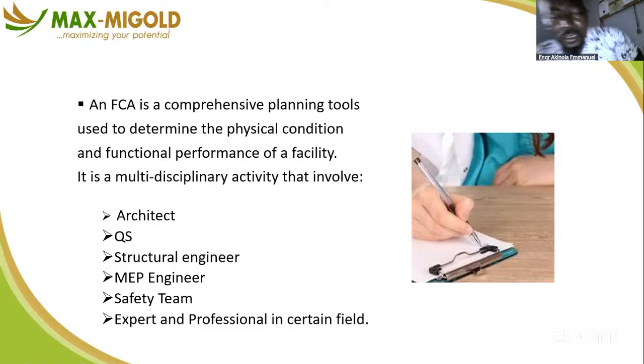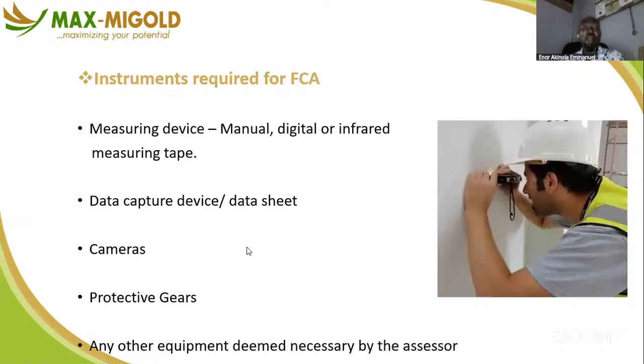You might need people to bring up possibly a drone for you to assess the external side of the whole skyscraper. For the interior, you can make use of your lift to take you to each of the floors. But in case you don't want to spend money on scaffolding, you can get a company who has a drone to help you do the external assessment or the roofing assessment of that facility with the aid of the drone. And this company must be able to give a detailed report after the assessment.